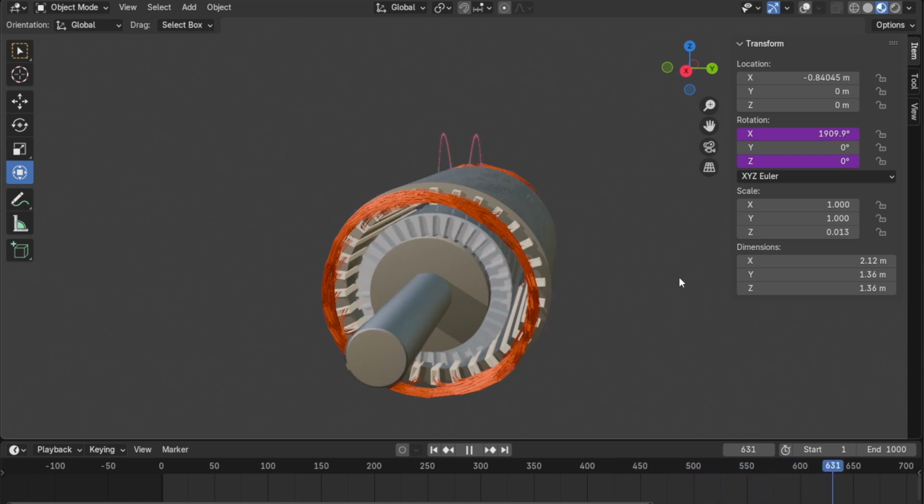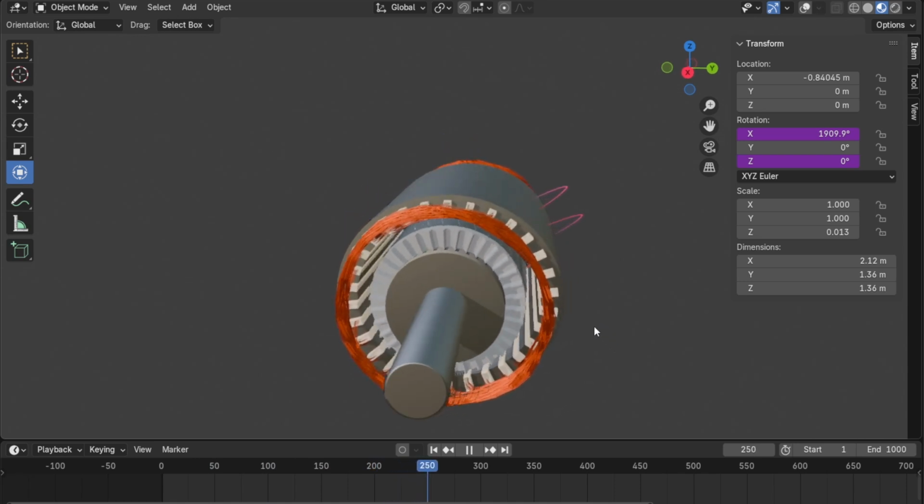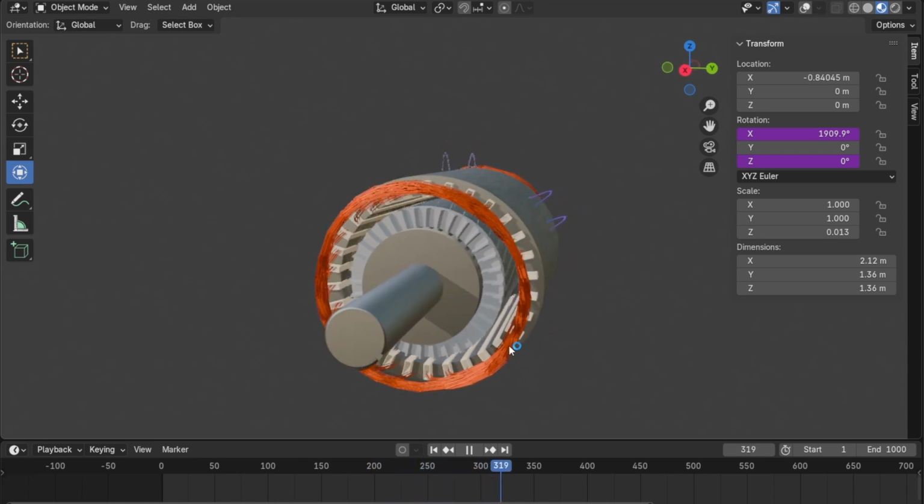We get an increase in rotor current and also stator current. The rotor currents somewhat reflect back onto the stator again. It's just like a transformer. When you load down the secondary, the primary feels it. The secondary impedance gets reflected back onto the primary. And that's why the primary can also be damaged if you short the secondary of a transformer. And so, even though these fields are weaker now, our rotor is a lot slower. Our slip has increased, which means the rotor will be robbing more current from the stator. And thus, the stator will also draw heavier current.